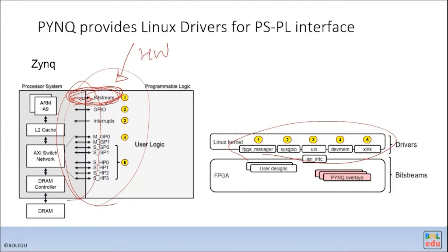There's some controlling logic here to take the data from the file. You have a bitstream file in the file system. When you load the data into the memory, how the memory data gets into the FPGA and programs each SRAM bit, there is certain controlling logic here, and I don't see documentation on that.